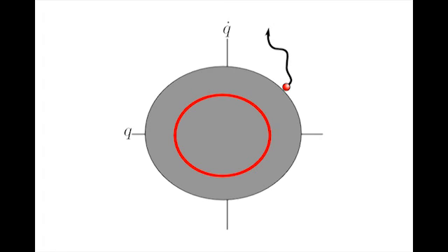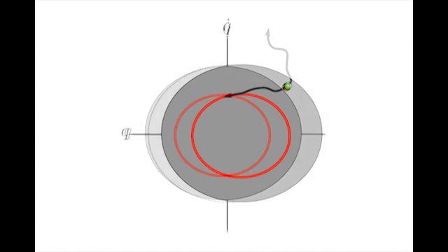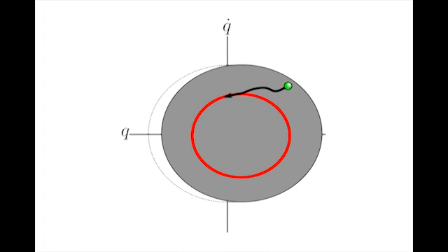Sometimes the starting state of a motion is so far from the limit cycle that it cannot converge, for example, the red point. We can resolve this by transforming the underlying state space. The transform is called an action and can incorporate user constraints such as position, speed, or energy into a system.